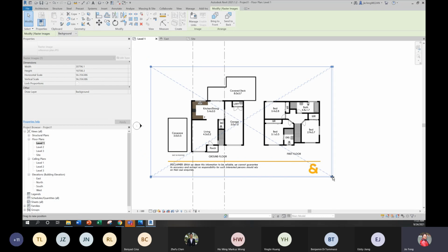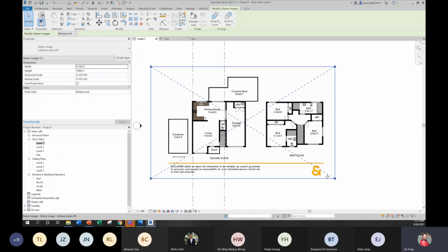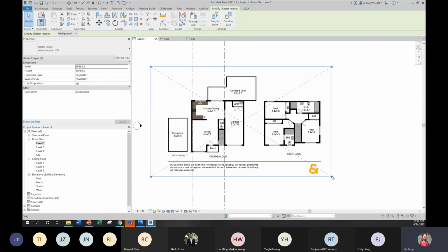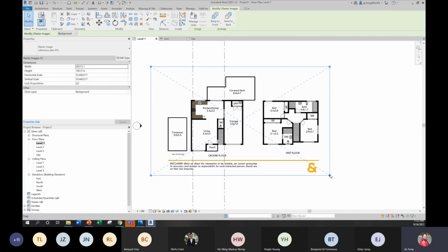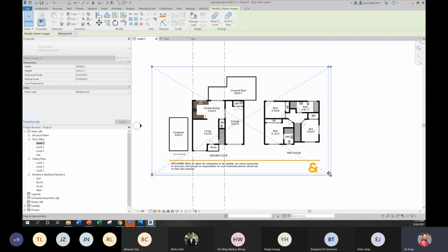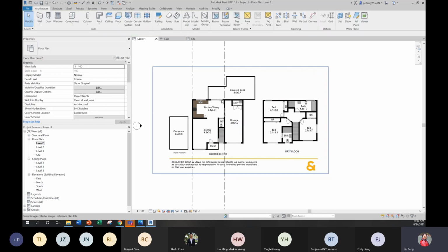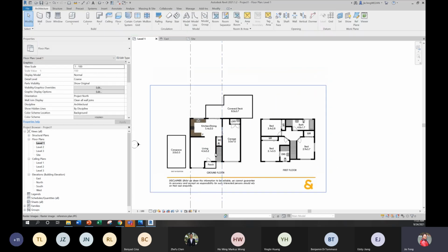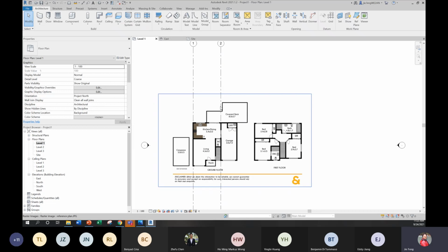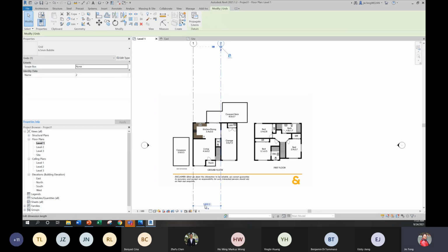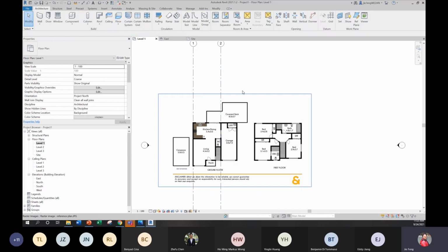Let's scale this one to match the distance between the grids a little bit, because that should be 5.2 meters. A little bit. Yeah, I think we are almost matching with the base map. So now the distance here is 5.4 meters, right? And we're doing the same thing for this wall and all the horizontal things.